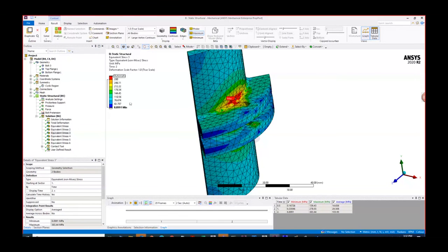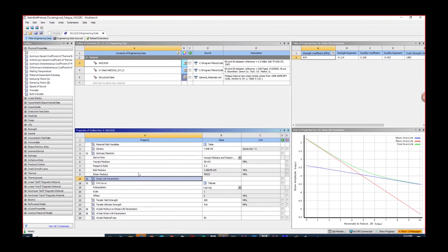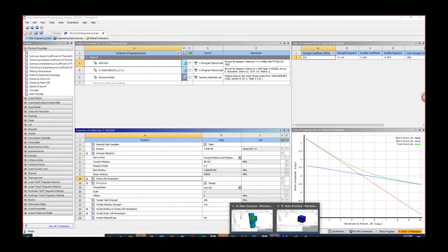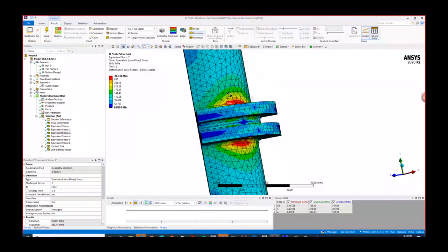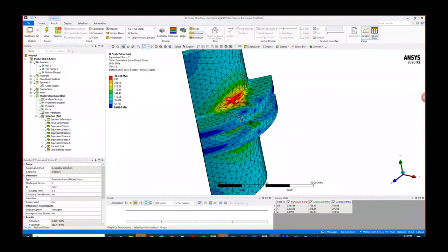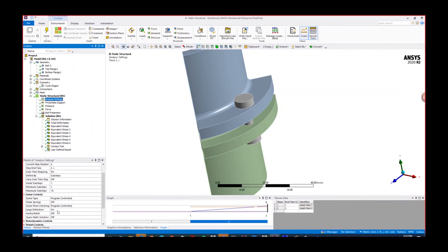One way to handle this properly is to include an elastic-plastic material model for this material and calculate the plastic strain, but that is a time-consuming analysis. So in order to save time, and since we know that the plastic strain is local, it is probably acceptable to use some kind of plastic strain correction. So we are still carrying out a materially linear analysis, though we are considering geometric nonlinear analysis, with large deflection on.